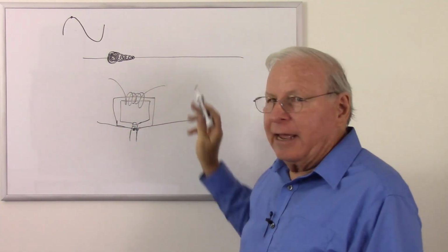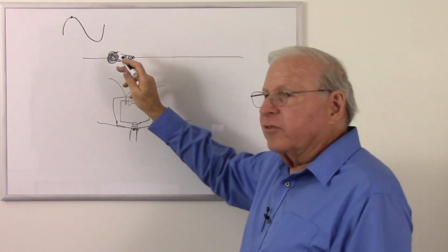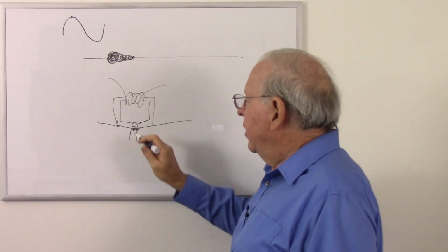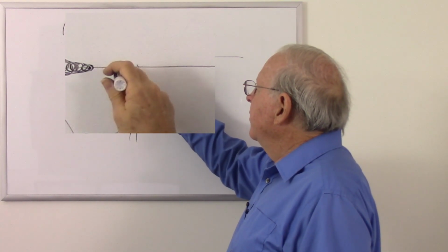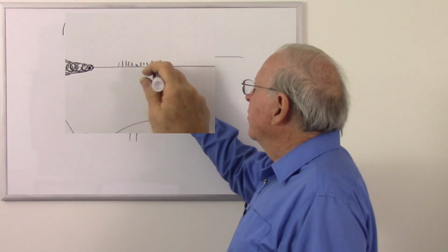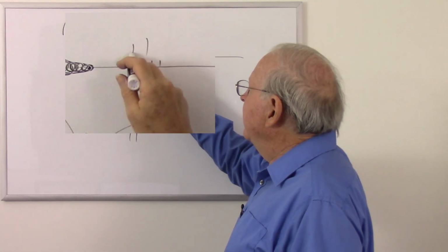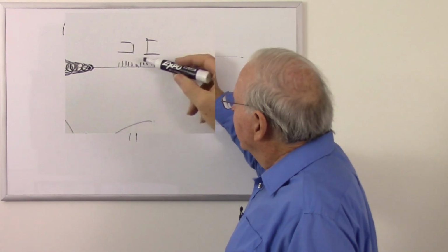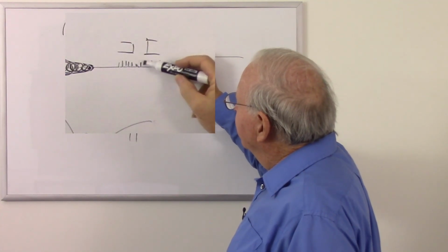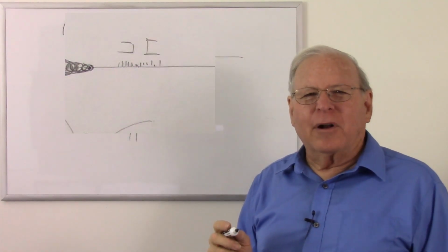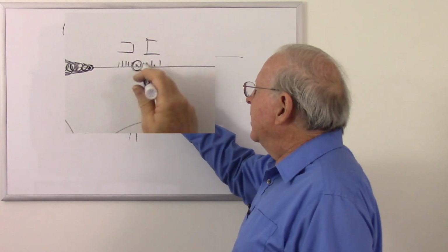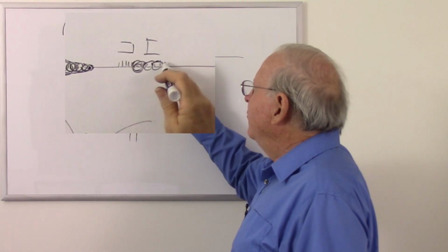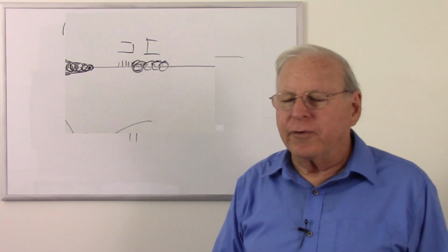So we need to move that tape by very quickly to reduce that overlap, because our higher frequencies take up less space on the tape. Let's say we've got a whole bunch of domain changes like that, and the gap is this wide. Well, we're trying to magnetize parts of the tape that are much smaller than the gap, and the gap is going to say, no, you're going to magnetize parts of the tape that big. As you can see, the high frequencies just aren't going to record.